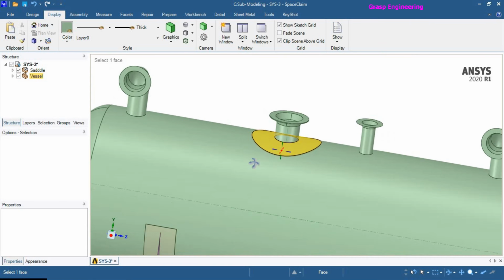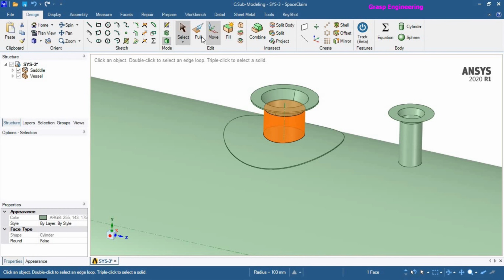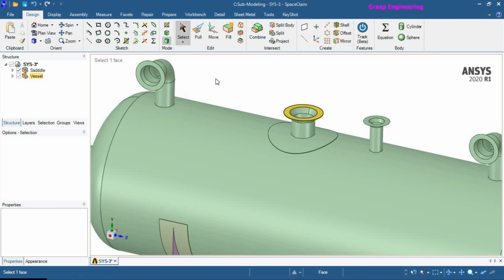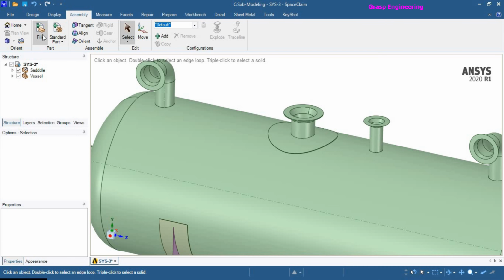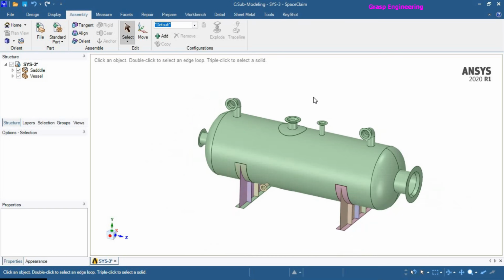In order to obtain this model, you just go to Design and use the spool option. You spool that and increase the thickness, whatever the thickness of your vessel, accordingly up and down on both sides. So you will get this respective solid model part. Or else you can model that in a different software and import that file from assembly, and here you have an option of importing your respective file. But it is better to have the same file from the existing analysis system.